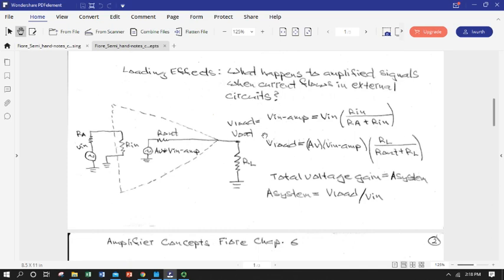So there's a mathematical example of why we want big input impedance, low output impedance. But nonetheless, in the real world, we don't have infinitely large and small values. Even though they can approach ideal, they typically aren't. So we're going to remember these equations and use them in some examples to see what happens to our real gain, our system gain, when we have real live inputs and loaded outputs.